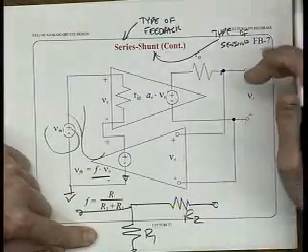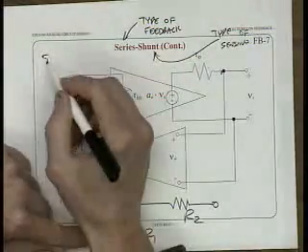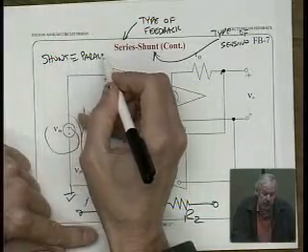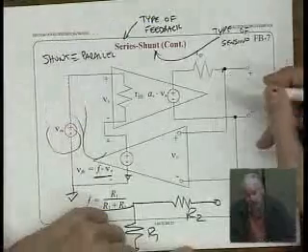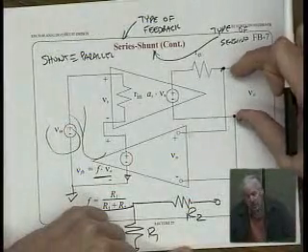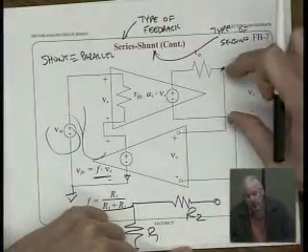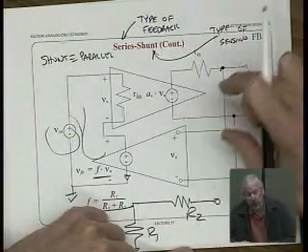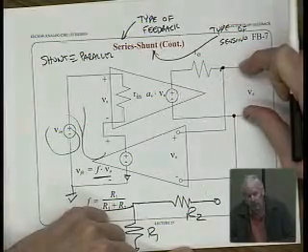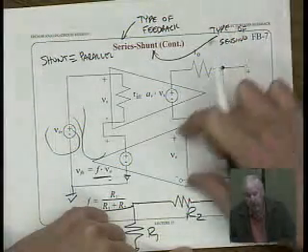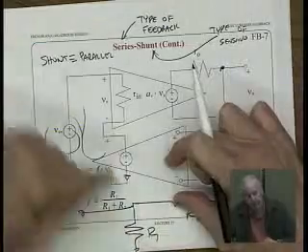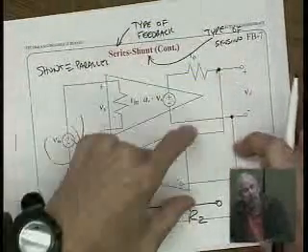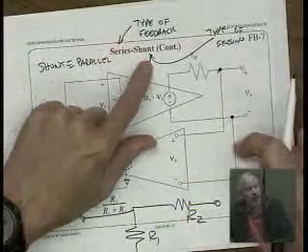We're sensing. Shunt means parallel. Shunt equals parallel. The input to the feedback network is sensing the output of the basic amplifier in parallel. See, it's in parallel? Okay. So this is in series, and this is in shunt, parallel. So we call it series shunt feedback.